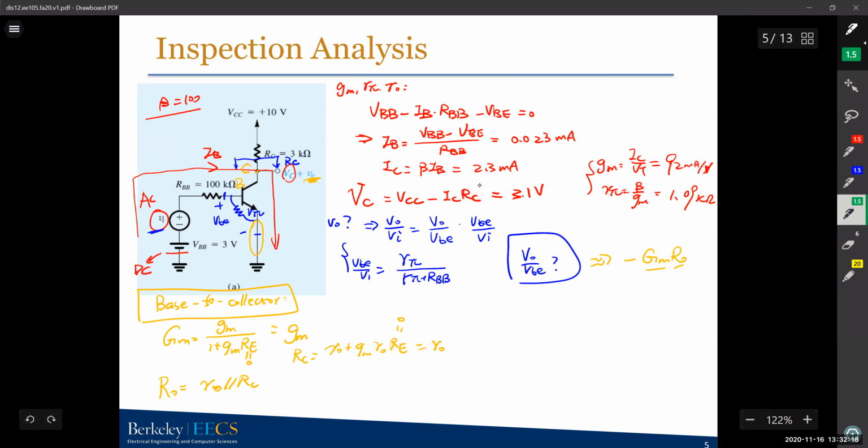So you have an R small c. Okay, I'll draw it in another position. So you have this R small c here, the equivalent resistance, and you have an R capital C, the upper part, and this is your V out. So the equivalent resistance or output resistance here will just be R capital C in parallel with R small c.